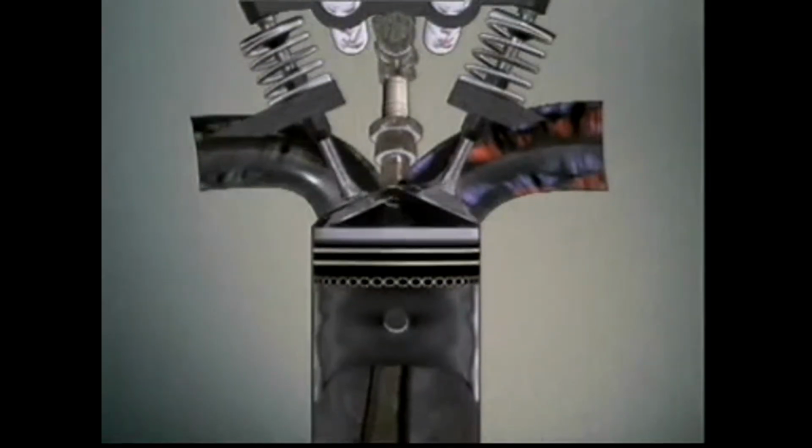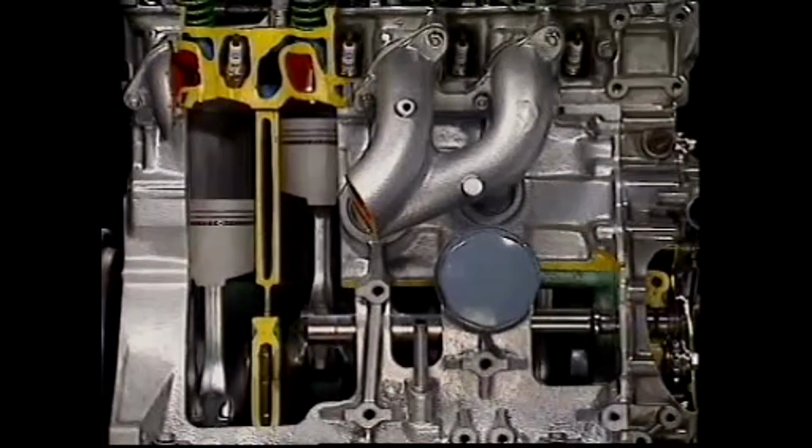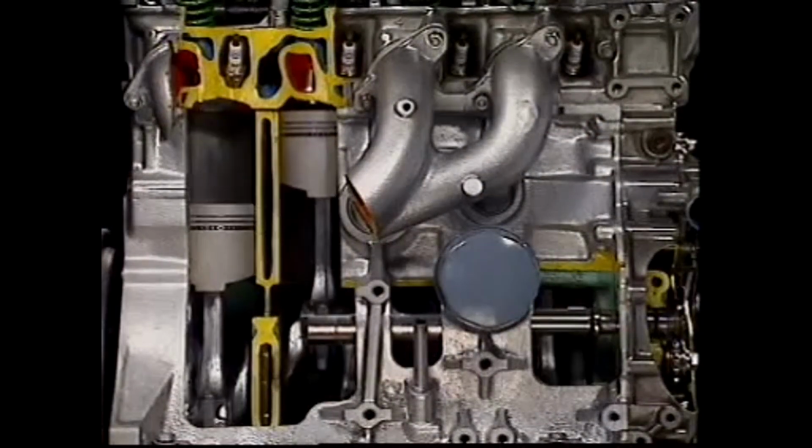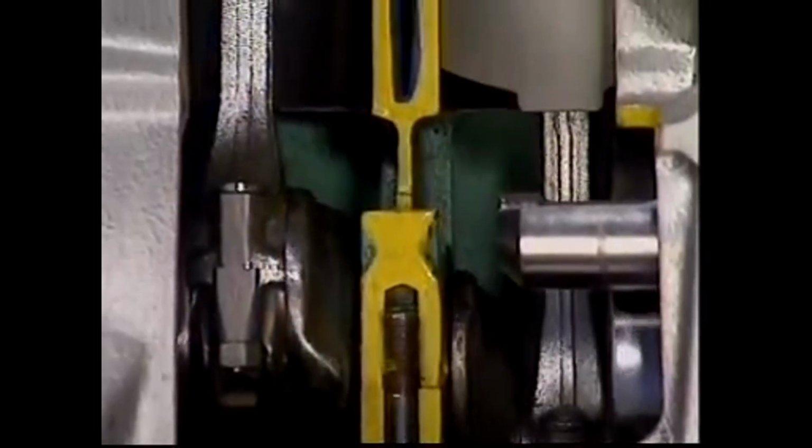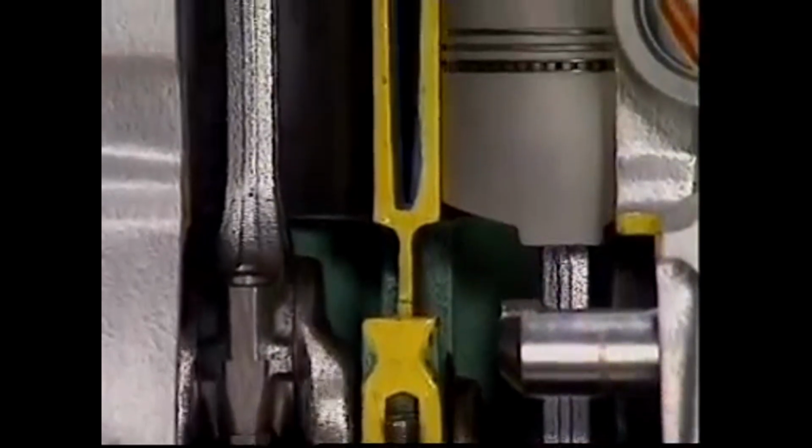The crankshaft forces the piston back up the cylinder, pushing leftover gases out past an exhaust valve. And everything is back where it started, ready to repeat the whole process. The whole process is a cycle. A new mixture enters and is ignited. Combustion occurs. Expanding gases drive the piston down and turn the crankshaft, which pushes the piston back up the cylinder.